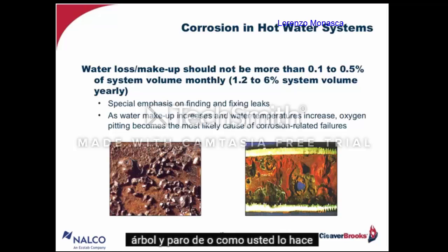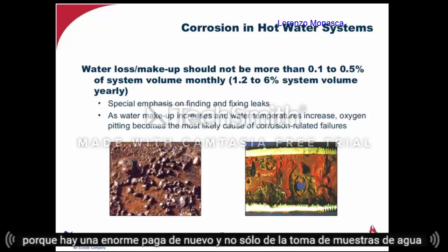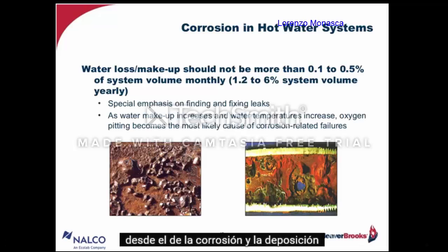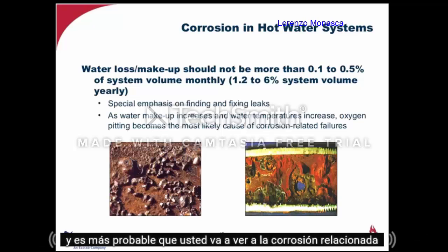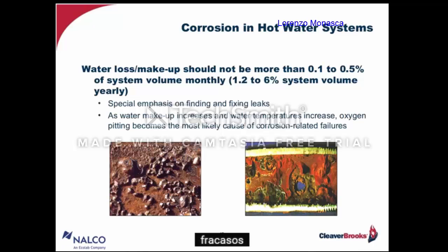And so however you do it, focus on finding and fixing those leaks, because there's a huge payback in that, not only from the water standpoint, but also from the corrosion and deposition standpoint. As makeup water increases and water temperatures increase, oxygen becomes even a bigger problem from the standpoint of pitting, and it's more likely that you're going to see corrosion-related failures.